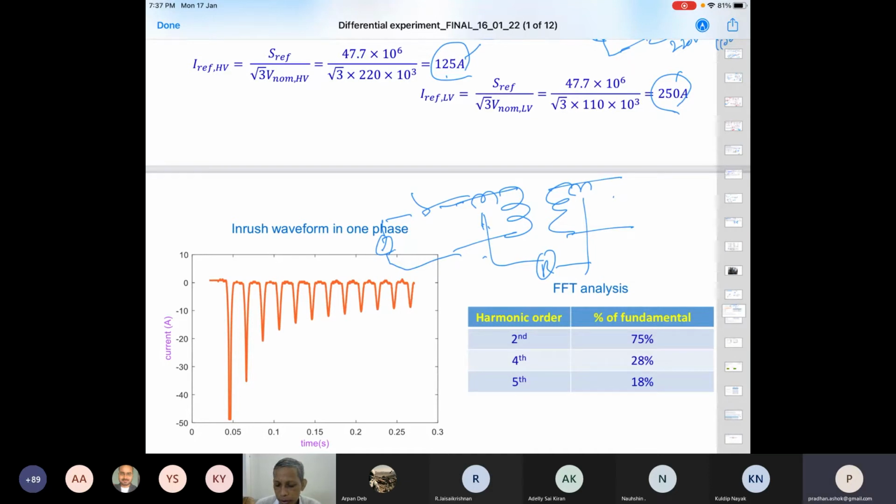So what will happen, because this flows on the primary side, and there is no current on the secondary side, or under lightly loaded condition, negligible, small current. Therefore the differential current will be significant. All of this current will flow to the differential branch. So the relay operating quantity becomes significantly high.